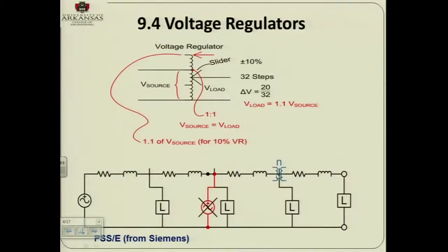This source is representing the ideal voltage source, your infinite bus, referred to the secondary side. So what you do is you calculate, your feeder is given, and you calculate your R and Ls, and here you calculate your R and L for the loads, and basically you run PSpice, and then remember that this is an AC source that you have to input the peak voltage per phase. Remember, this is one phase of your three-phase system.